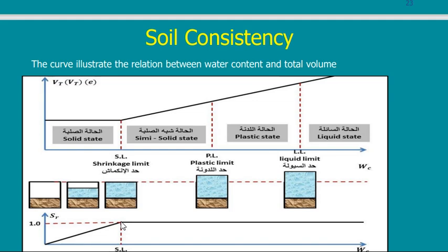Then whenever I add more water, what will happen? The degree of saturation will not increase because it is still fully saturated, but the total volume will increase. The whole sample will expand. So this is what will happen.